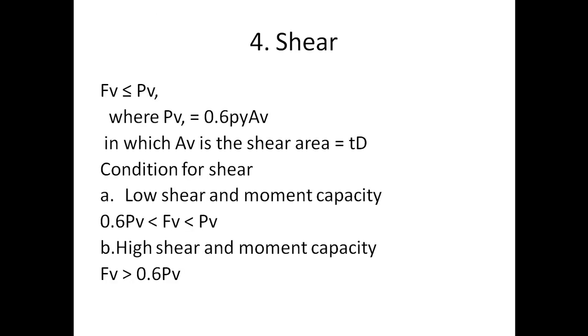So the next thing is our shear. You have to determine your shear. You can see the simple formula for determination of shear. You can see your FV, which is your shear load, your shear force we got from the shear force diagram earlier. And the PV, our PV is given here, is needed also for many things.